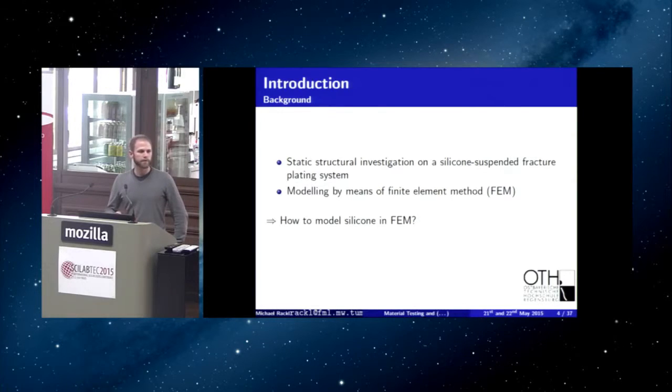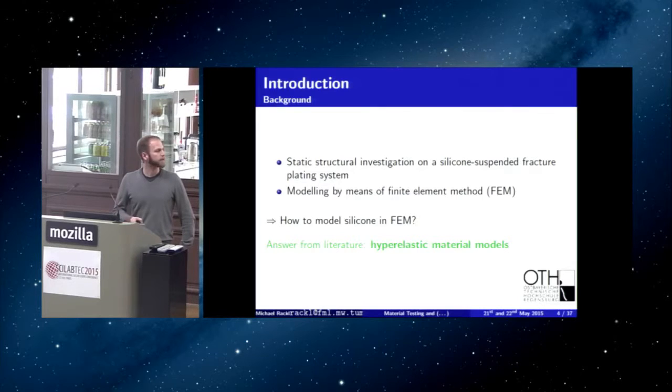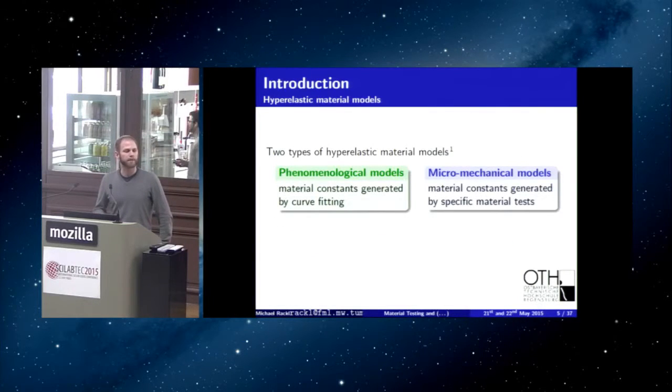The method we used to do the computation was the finite element method, which is really common in mechanical engineering. So the first question I asked myself was, how do I model silicone using the finite element method? The answer from literature: use hyperelastic material models. Next question, what are hyperelastic material models?